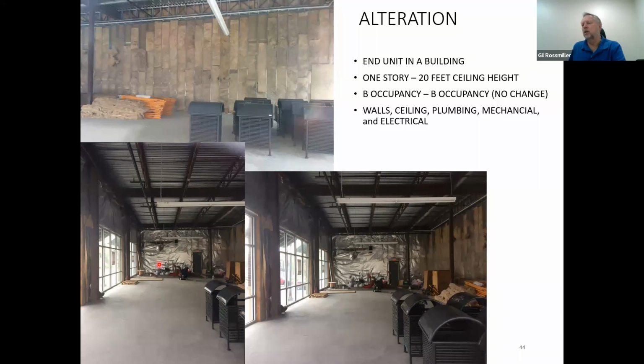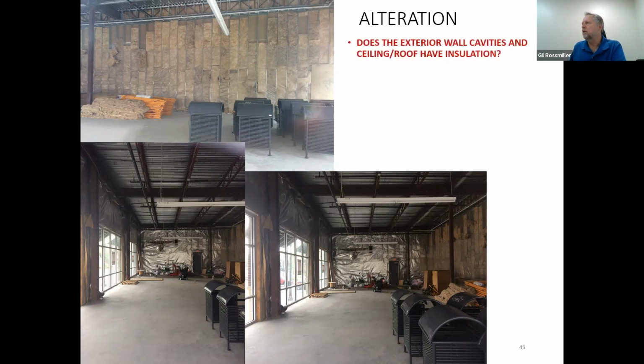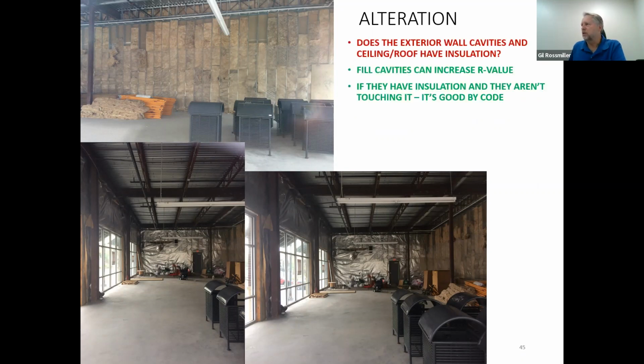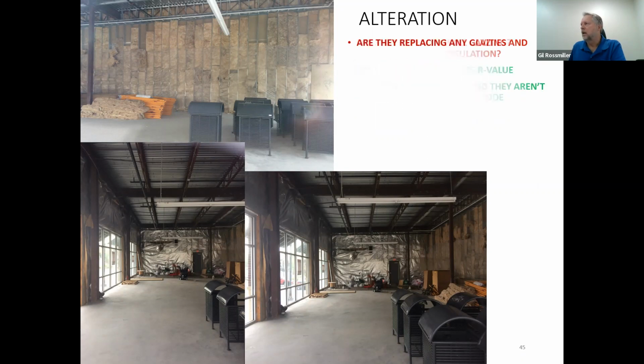So here, probably the biggest thing to stress is that the thermal envelope has got to have already been done, right? Because if it's not done at the shell building, you're out of luck. You're never going to get there. Do you have cavity insulation? Fill the cavities.